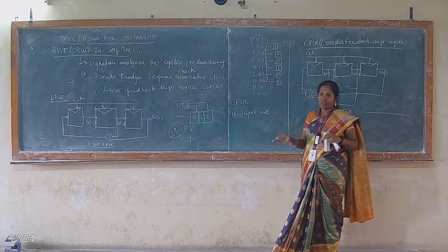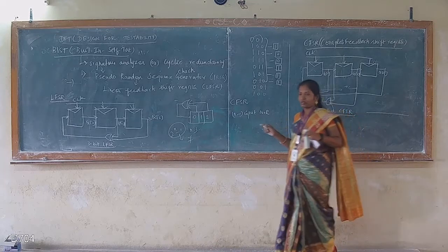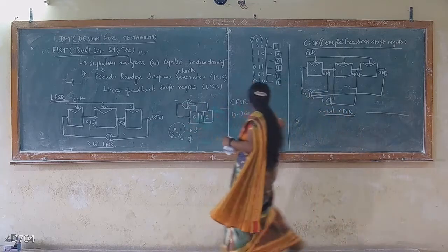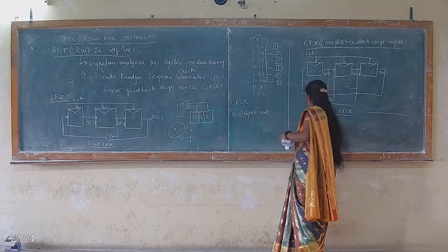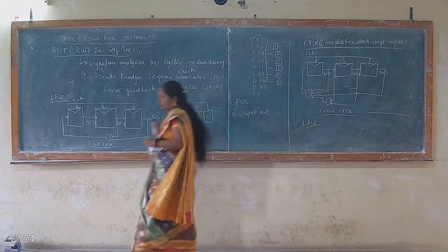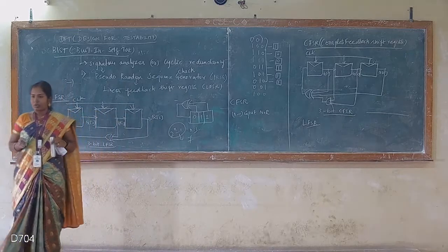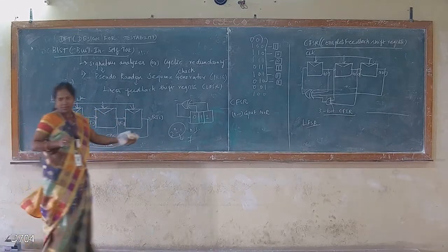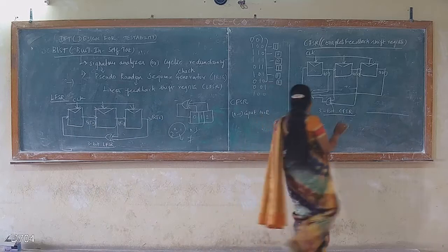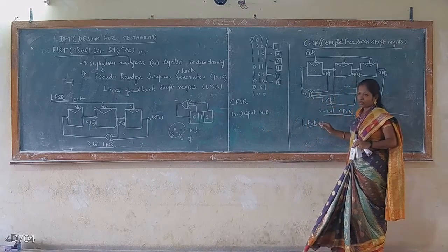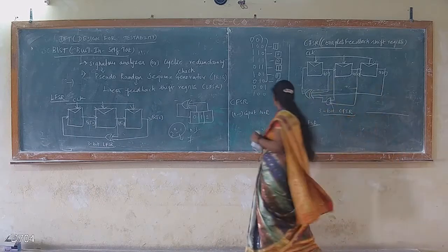Then it is XORed with the output on every cycle. At the end of the sequence, the LFSR contains the syndrome, which is a combination of all previous outputs, and it is checked against the correct syndrome to check whether the circuit is good or bad. So this is the process of BIST.